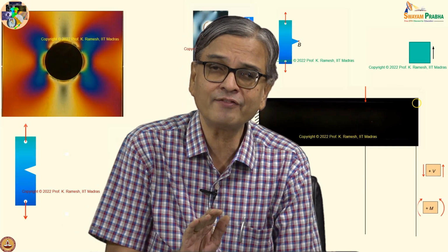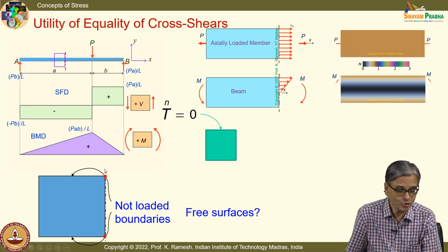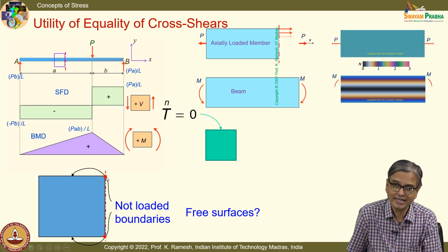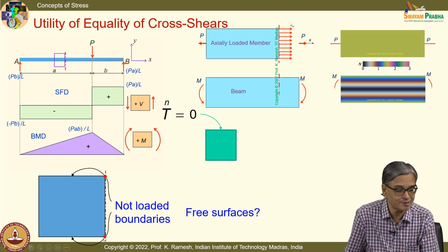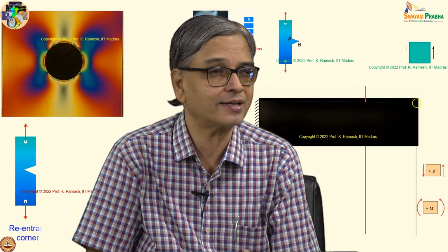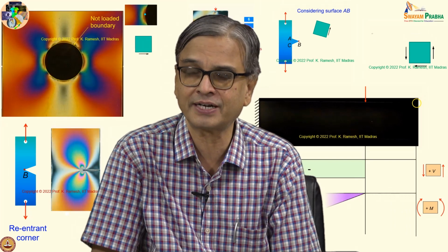So, at this level of course development, you can confidently say, yes, I am going to have a shear stress distribution on the cross section. It has to be 0 at the top point. Extending the same logic, it has to be 0 at the bottom point. In between, what happens? Let us postpone it. At least this I can confidently say from whatever we have developed.